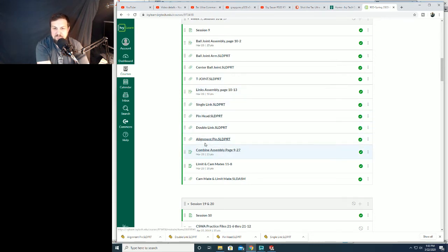So let's go ahead and we'll talk about assemblies a little bit. So assemblies in the world of CAD. An assembly, we've talked about parts already, and we've been working with parts. We've been creating these parts using features, right? The features are like extrudes and cuts, all of these tools that we've been working with so far. So an assembly is where you take each one of those separate parts that we've created so far, and we put them all together, and instead of adding relationships like we do with lines to create a sketch, we're going to be adding mates.